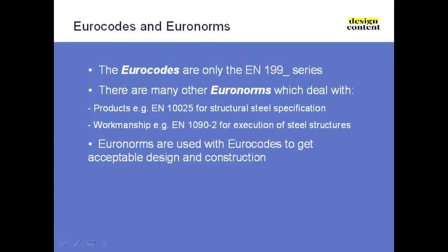It's very important that you do use the Eurocodes with the Euronorms. So we can't mix old product standards, for example, because a lot of the increased resistances that come in the Eurocodes are there because of modern fabrication and modern materials. And this is one of the dangers of trying to apply Eurocodes for assessment. We can talk about that later on, but Eurocodes specifically do not cover assessment because the rules do not necessarily work with old materials. But that actually doesn't mean that you can't use the Eurocodes for assessment if you know what you're doing and you understand the old materials.